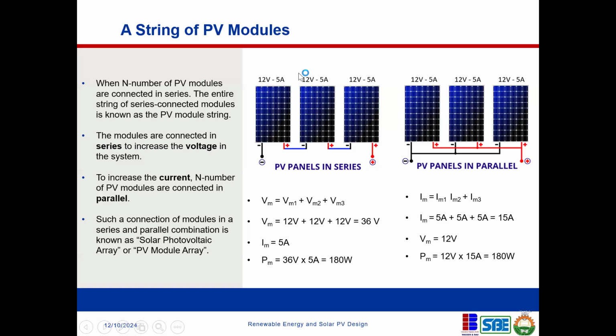What's going to happen to this entire series connection is that they are all going to be reduced to 20 watts. Meanwhile, this ideally should come out at 180 watts, correct? That's the three of them combined should come out at 180 watts. But I think 20 watts is even too much. Maybe this cell is contributing 5 watts or 2 watts, right? If dead leaves cover this cell, it's going to reduce the entire output to 5 watts.